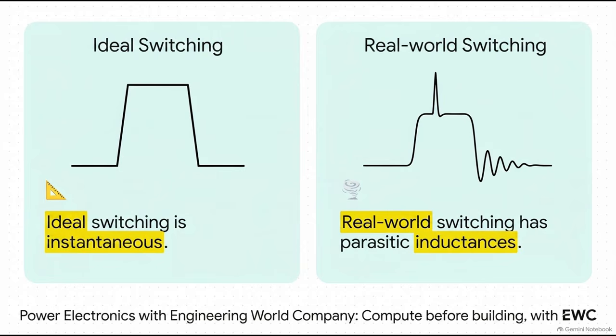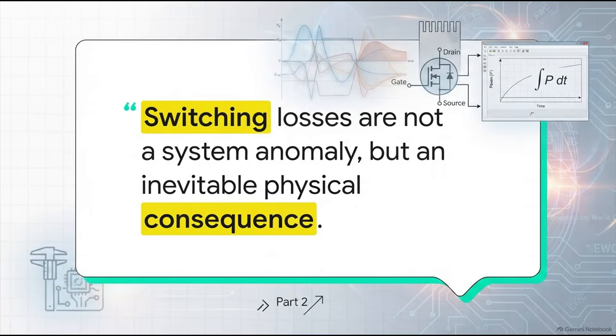And this is exactly where a tool like QSPICE shows its unique and powerful strength. It lets you inject those parasitic inductances and distributed capacitances directly into the simulation. That means you can accurately capture these non-ideal waveforms way before you ever print a physical circuit board.